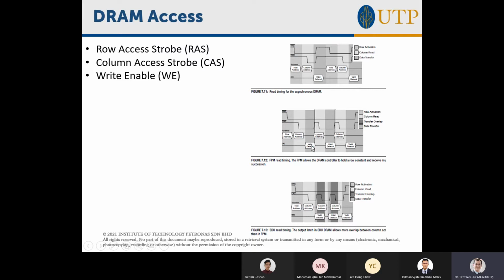The problem is every single different address you want to read, you have to put in the row and the column address. So if you have a 16-bit address, you're actually changing 16 bits in one go, 16 bits for every single address you read. And again, every bit you change requires energy. So you have 16 bits of energy changing all the time, and then you have to wait for these long lines to settle.